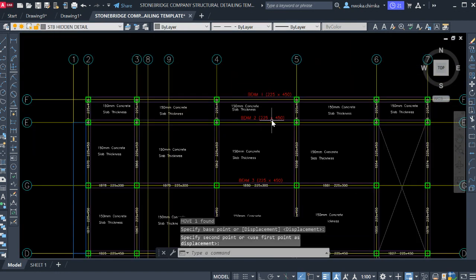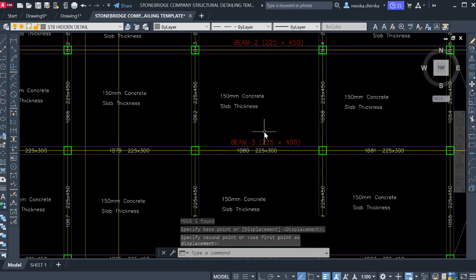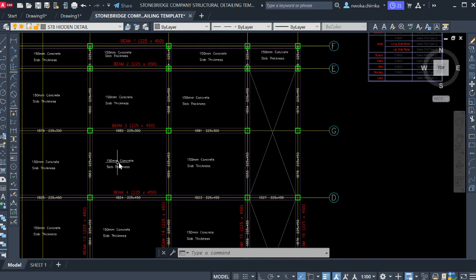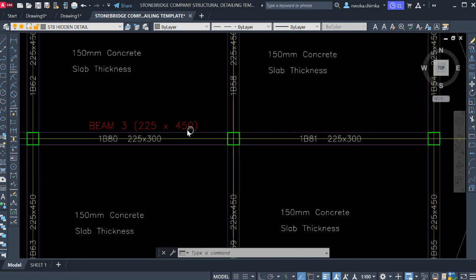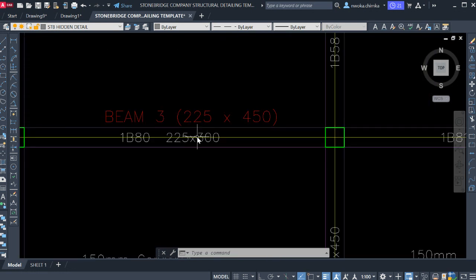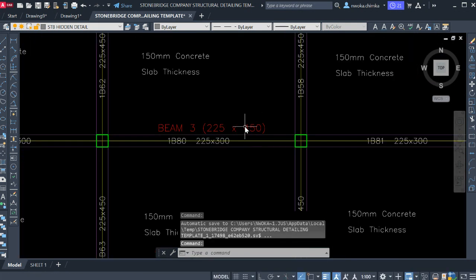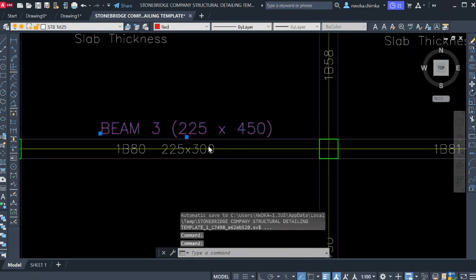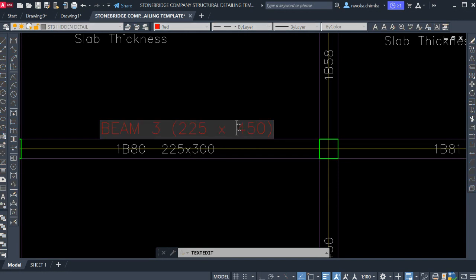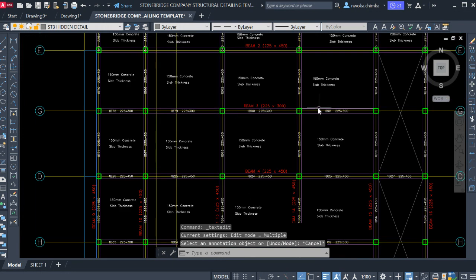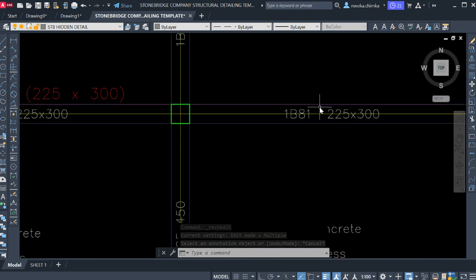Okay, so right now we will go for bin 3. Bin 3 now starts from 78 to 70. Now you can see that this beam size is 300. So I'll quickly change this just now. That's why I say you should also always check. I'll change this one to 300. You can see this beam size 300, so this beam depth is 300. I'll change to 300, and then I'll locate beam 78 to beam 81.